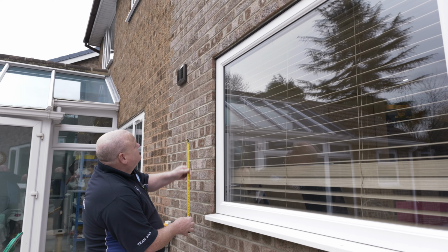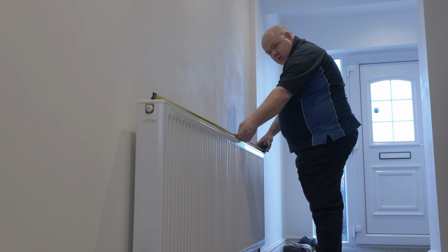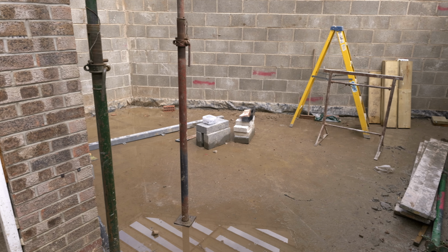We're going to measure windows, rooms and radiators, and look at the thermaskirt as well, and how that will work with the new system we're going to put in. Also in this area, we're going to put underfloor heating in, so again, we're going to show how that will work. So let's go inside and do a full heat loss.